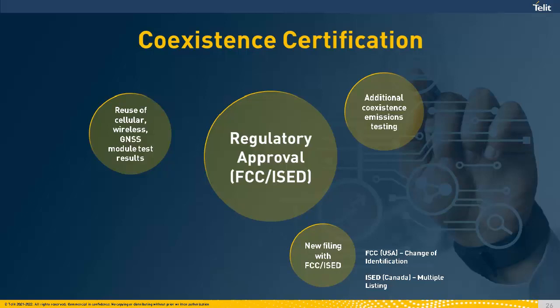And in particular, regarding the regulatory approvals like FCC or ISED, that is simplified when using a pre-certified module. For example, for the FCC in the US, the change will require only a change of identification instead of a full FCC activity, while for the ISED that will be a multiple listing, just another listing of this technology, alongside your application.